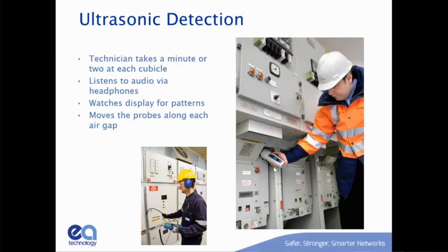And you've got this airborne or air-based microphone, and you're going to try and find an air path from the source to the sensor. You know, lots of switchgear has vents, louvers, gaps around the doors. Sometimes these doors don't fit very well. Some way in. You don't need a direct line of sight, but you do need an air path between the source and the sensor. Just like if you were listening to me, you need to have an air path from my mouth, which is generating the signal, to your ears, which are listening for it.